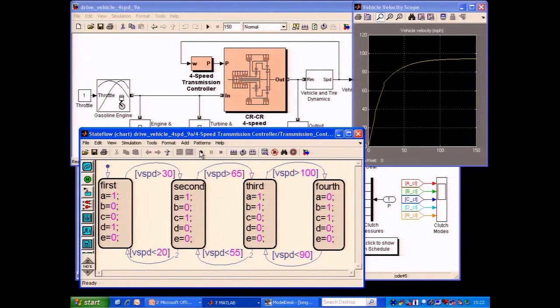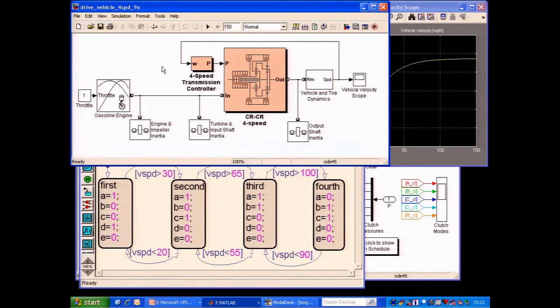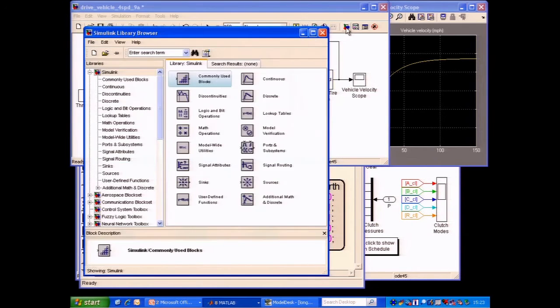So to give you an impression as to how the physical modeling method works, in this drivetrain there's a component missing, or perhaps I have new technology that I wish to add. So I'm simply going to delete this mechanical connection, and I'm going to insert another component. The component in this case is a torque converter. I'm going to pull this directly from the Sim Driveline library and connect it using the mechanical connections that we described earlier. Once those connections are in place, we can re-simulate the model and see the effect that it has